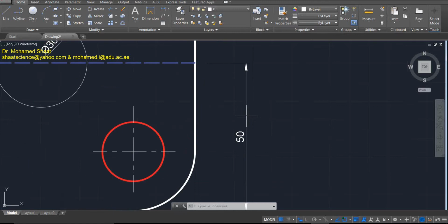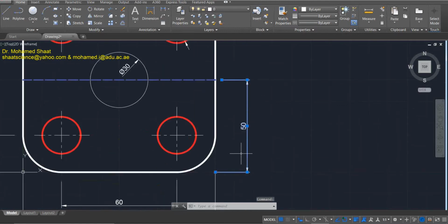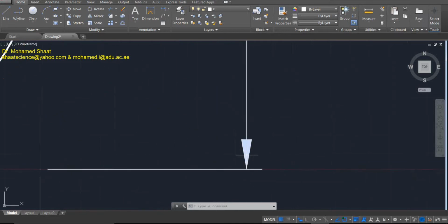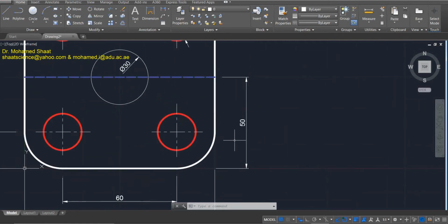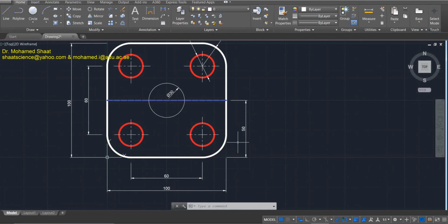The dimension would include, this is the dimension line, which is the arrow itself. In addition, as we mentioned, we do have the extension. Here we do have two extensions. These are known as the extension lines, in addition to the text itself, in addition to the head of the arrow. This is the head of the arrow, and this head has a length in addition to the width here. And all of these are standard. AutoCAD automatically defines these standard dimensions, but we can override these standard things to end up with a dimension that is consistent with the drawing.